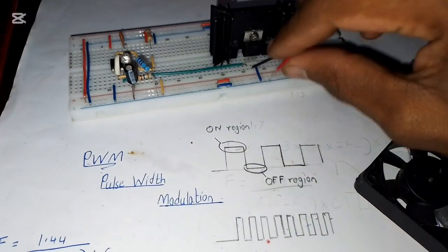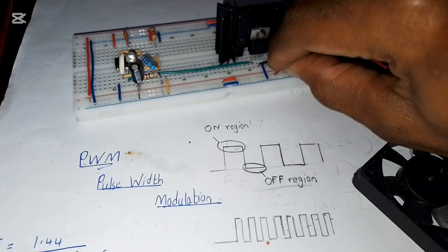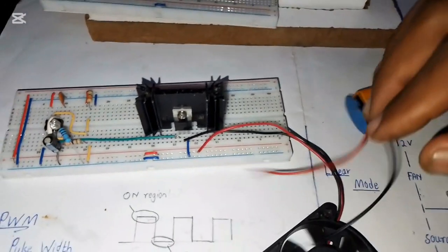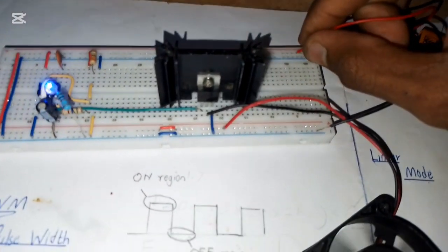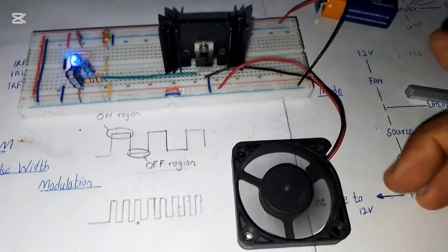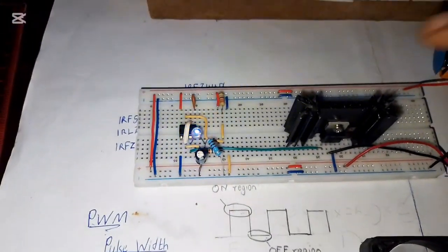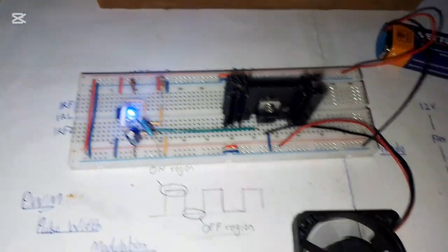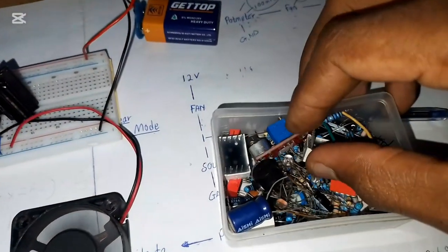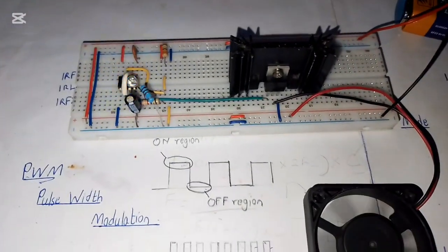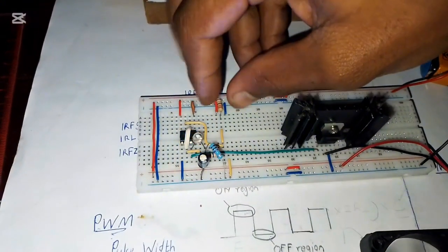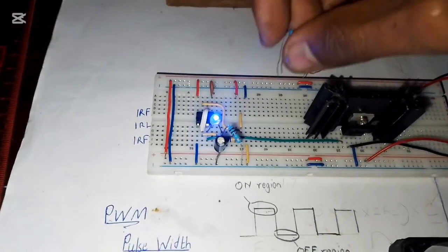Yes, so this is just connected to the positive like that, and we get our 9 volt power supply, which is basically a battery, and we connect the positive and the negative. Right now it will run at high speed because I'm using a very low resistance right here, R1. If we change it to a higher resistance, let me just look for maybe a 10K, you're going to see the difference. So this is a 10K, and I'm going to exchange this point to use the 10K.